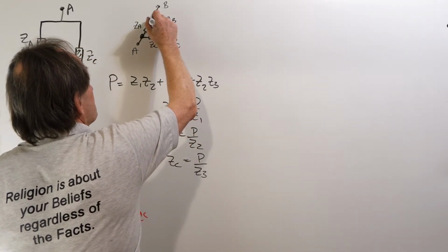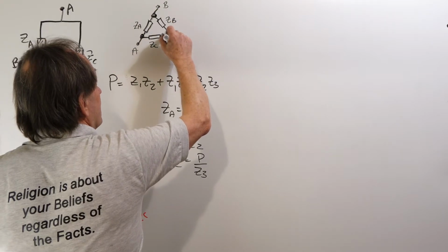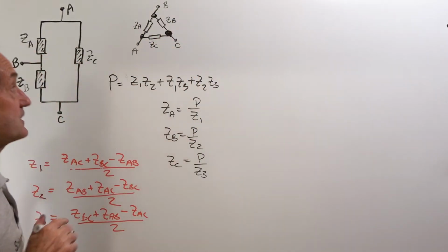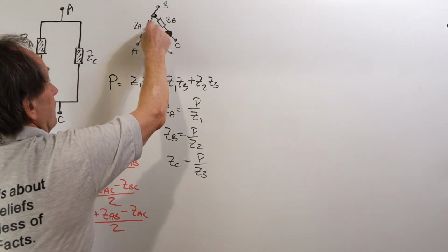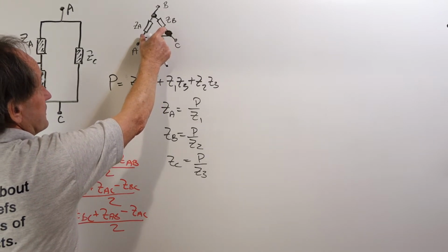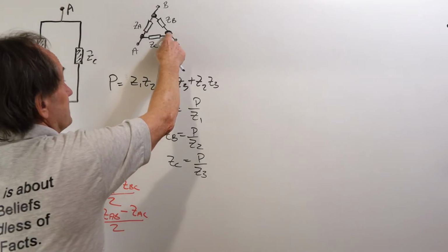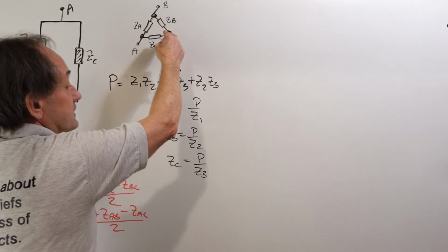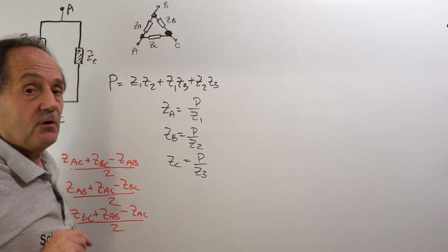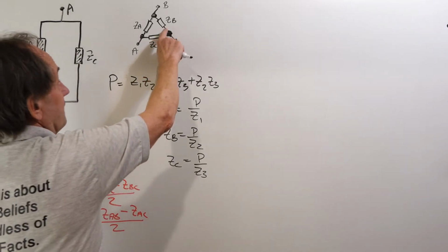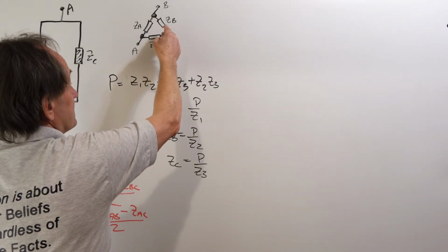Why I couldn't measure the resistors individually is, you could see the resistors were soldered very close together. So if I was to try to break one of the nodes, I wouldn't be able to put the network back together because there wouldn't be enough pigtail lead left on the resistors.